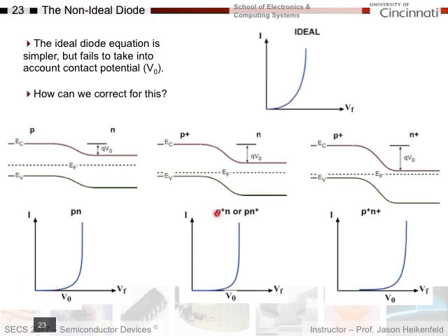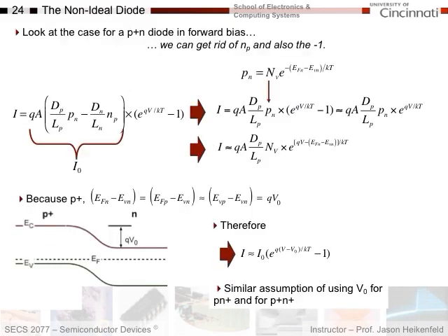You increase the doping levels, P plus or N plus, the contact potential shifts out, and if you make it heavily doped on both sides, we'll see the contact potential and the threshold to get current flow shifts out even further because I have a bigger barrier to overcome. None of these, of course, are like the ideal equation, which started right at 0. So let's do it here.